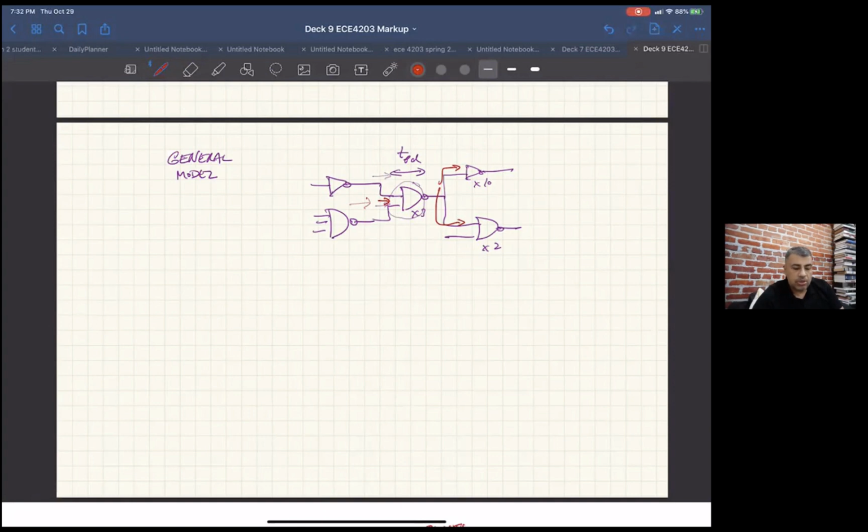Typically, the higher the input capacitance you have, the wider your device is, so you'll be able to have a smaller delay. But if what you're driving has higher input capacitance, then it's harder to drive, because you have to charge and discharge it. But the input capacitance is an indication of how much drive you yourself have.